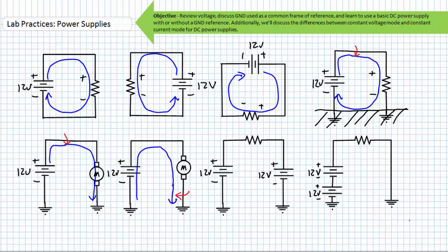For all intents and purposes, the low side switch is acting exactly the same way as the high side switch does. The only difference is that it provides a path to ground. The high side switch simply provides a path of connection to the source. Compare and contrast these two methodologies.